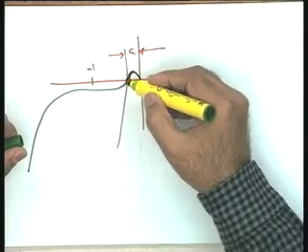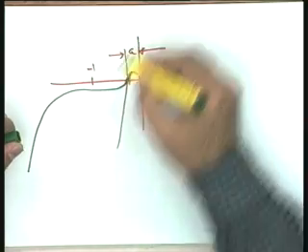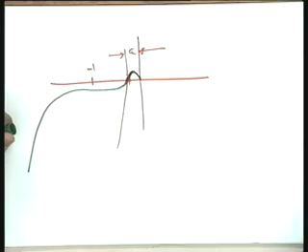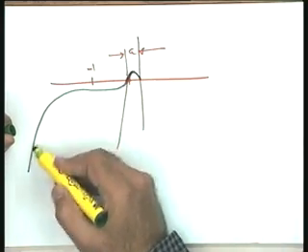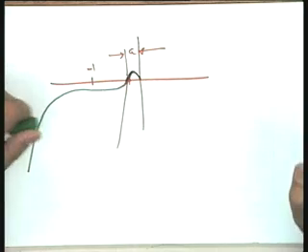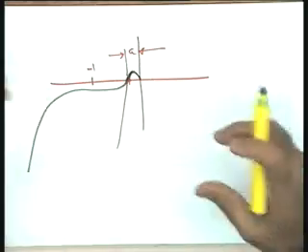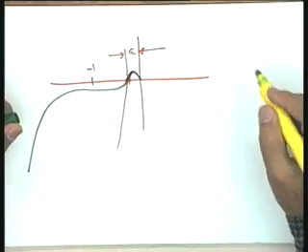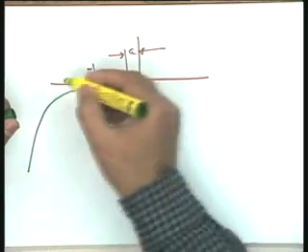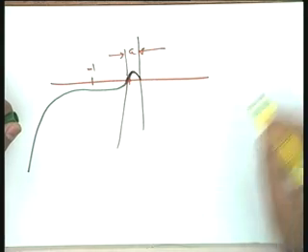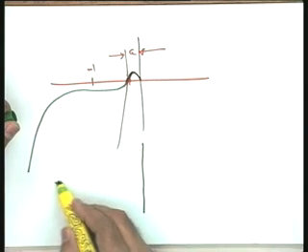So, in this particular case, though the intersection is the same, though we are far away from the minus 1 plus j 0 point as far as the intersection point is concerned, still you find that the green curve is more prone to instability because it is closer to the minus 1 plus j 0 point. So, it appears that the relative distance of the polar plot with respect to the minus 1 plus j 0 point cannot be given by just the intersection with the negative real axis. The phase angle is also important, and that is why two indices are used.